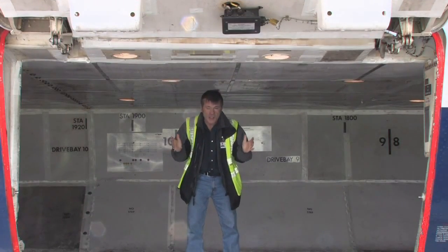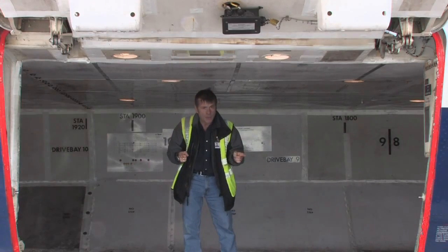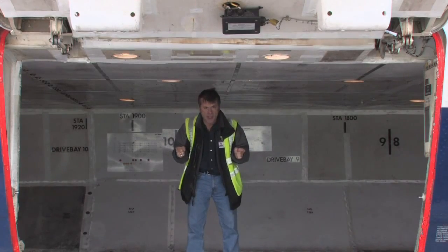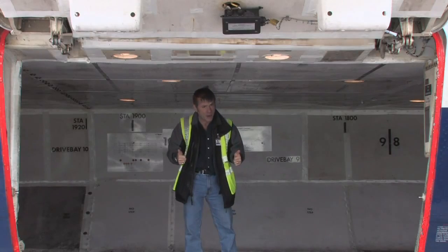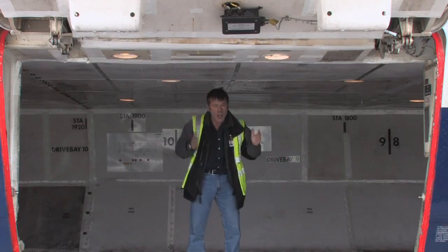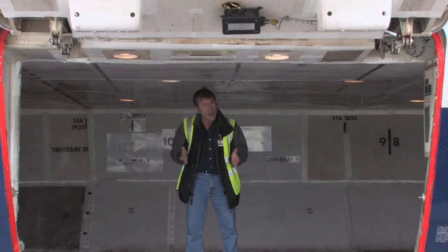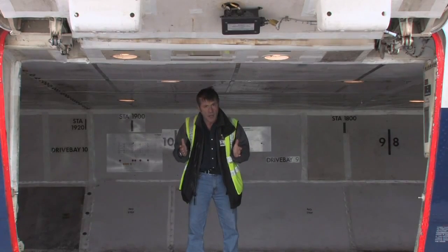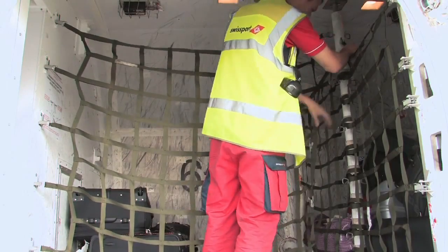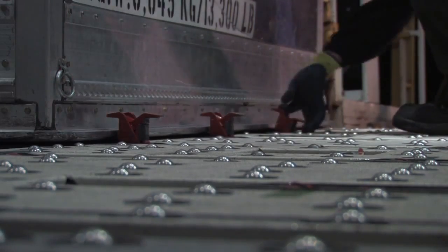Now, if the load is not adequately secured, strapped or locked, there could be trouble. Moving that around in here at 37,000 feet could damage the pressure hull of the aircraft. Definitely not recommended. Alternatively, moving a big load around in here can also change the center of gravity of the aircraft, the C of G, and that could lead to control difficulties or even loss of control. So before you leave the hold, make sure that all loads have been secured, strapped and locked down.